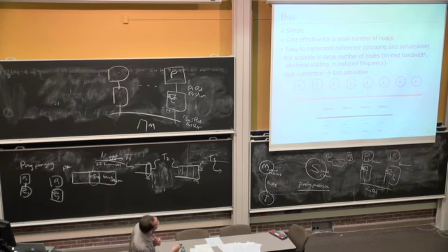As you add more nodes, there are two issues. First, you increase the electrical loading, which means that you cannot run your bus at a higher frequency. If you have 10,000 nodes, this bus will run like a dog. The other thing is, as you add more nodes, presumably they're going to send more requests, but you have only limited bandwidth here.